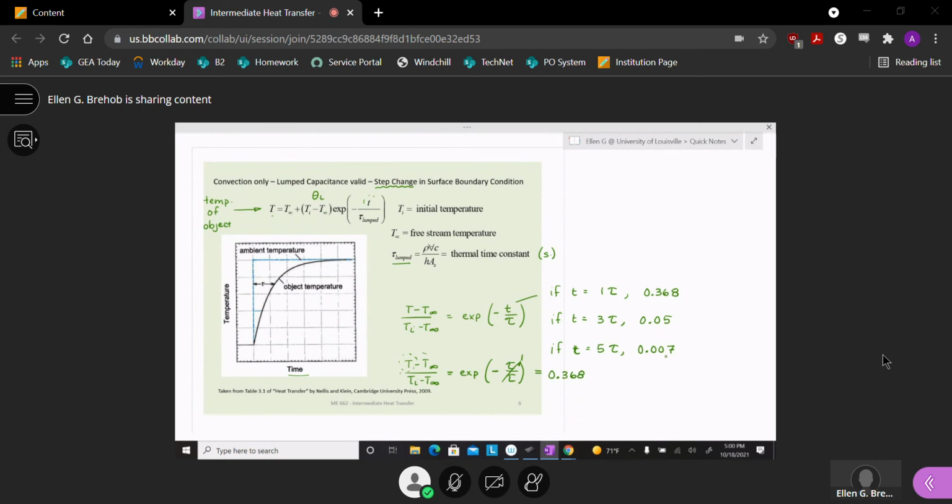All right, and I guess I started out because what was I trying to go? Some people remember that feature, and I've been impressed. I guess I know it now too because I've remembered it. But in the ballpark of 3 to 5 time constants, you should have reached your thermocouple. If you go 3 to 5 of those time constants, you should be measuring what you expect. You're getting very close to the air temperature.